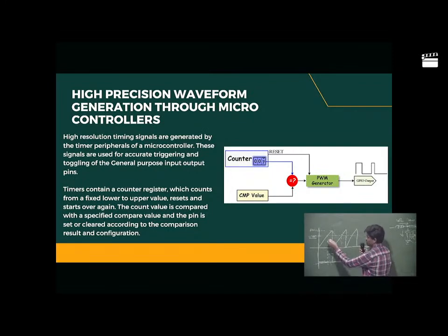You can even generate a sine wave by telling the compare value to be this at these discrete times, and you can create a sinusoidal pulse width modulation. So this is very accurate control. This is on a 16-bit counter. Some have 32-bit counters, 64-bit counters, because computation power has no limits these days. So each part of this can be very precisely controlled. This is how microprocessors do it, and you can absolutely control the amplitude and the slope.